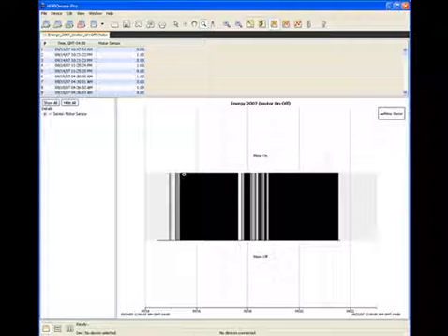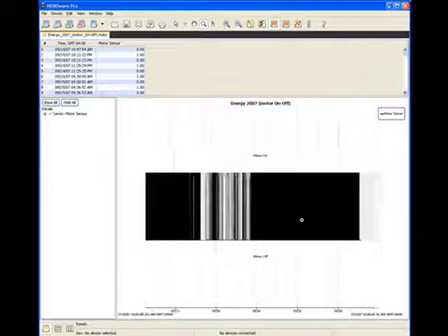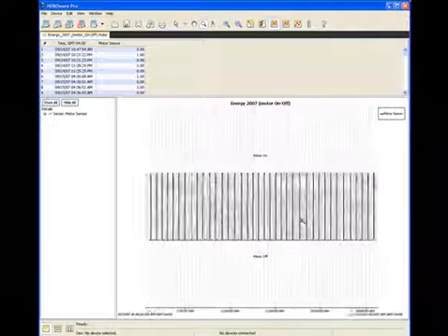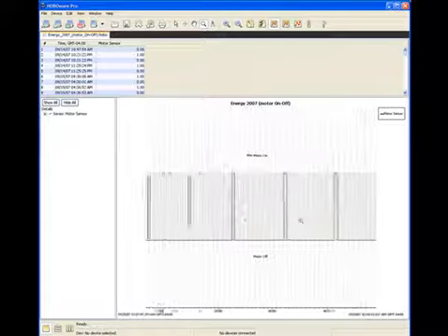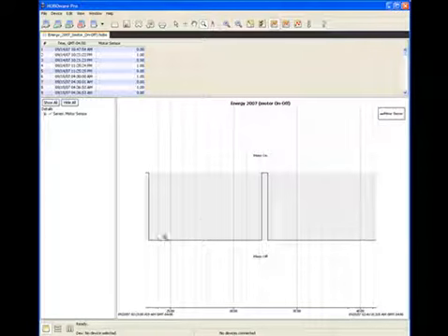I'm an application specialist at Onset Computer, and we're going to briefly talk about how to get valuable information from the data off the compressor. This is the resultant file after several days of deployment, and you can see that there are quite a few on-off iterations here. We can use the magnifying tool to compress our timeline, and what you can see is that we've had a lot of on-off iterations during the deployment, and they're fairly short in nature. This would represent the off time, and this would represent the on time.